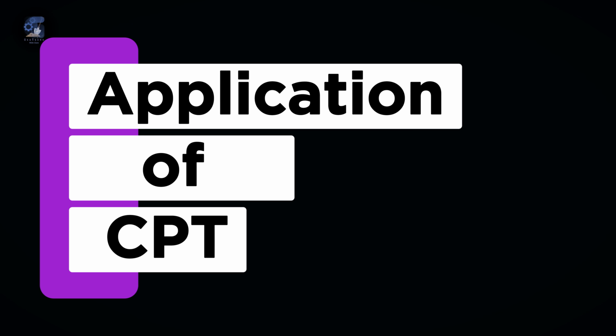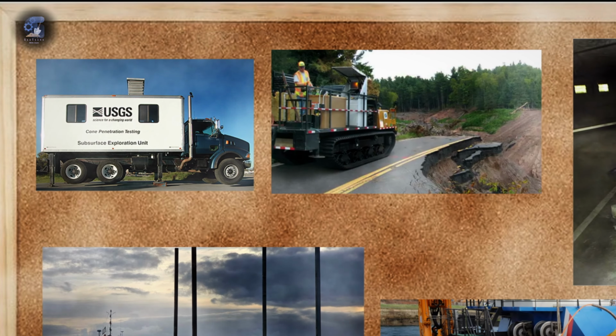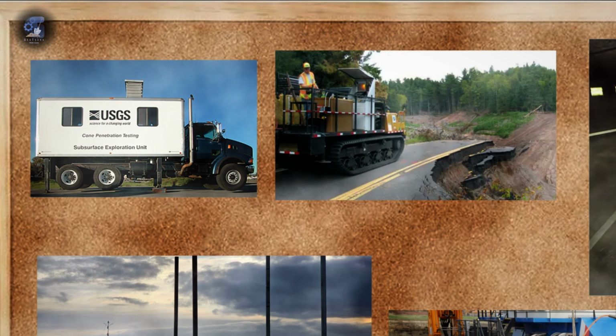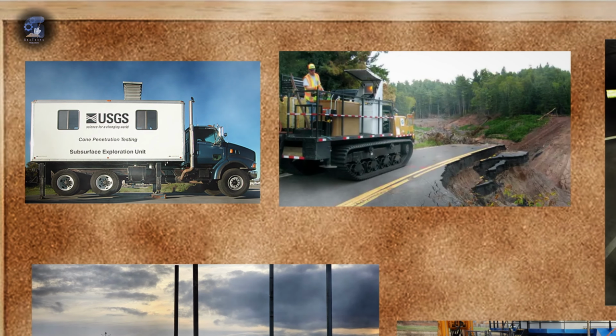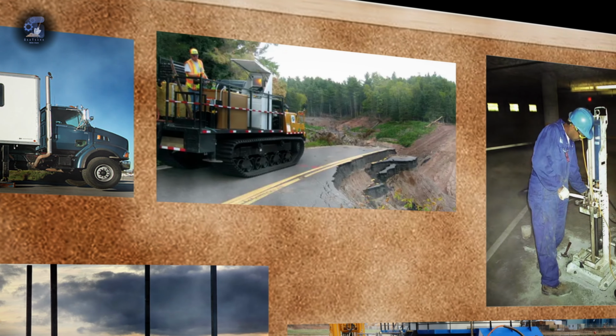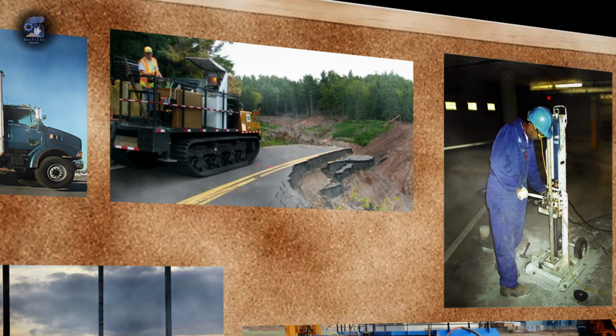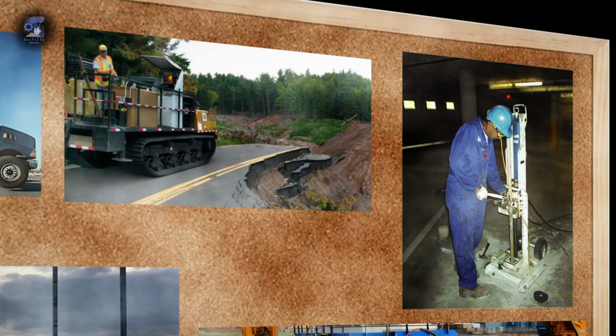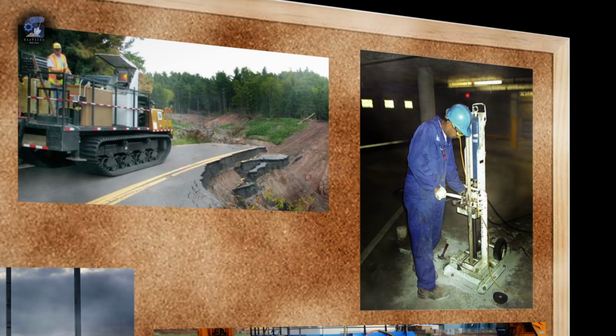One of the biggest advantages of the CPT equipment is that it can be deployed to many locations using a wide range of delivery systems. On land, this generally consists of a truck or a truck-mounted CPT unit, a small anchored drill rig, and even a portable ram set for CPT inside buildings or where there is limited access.